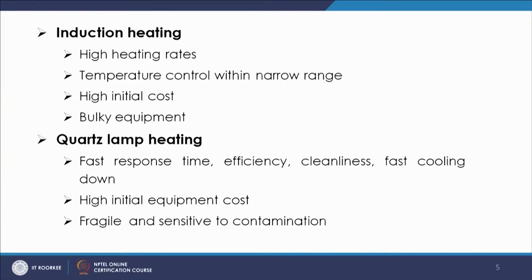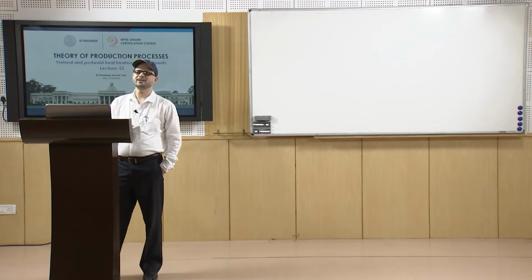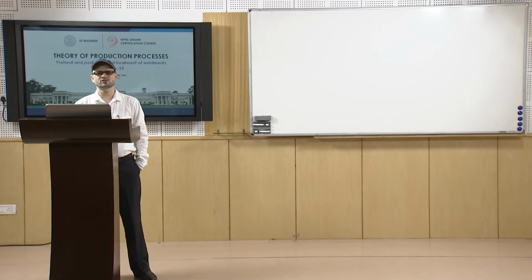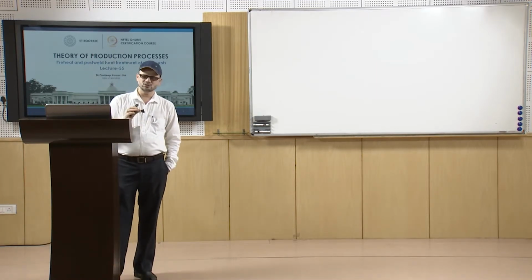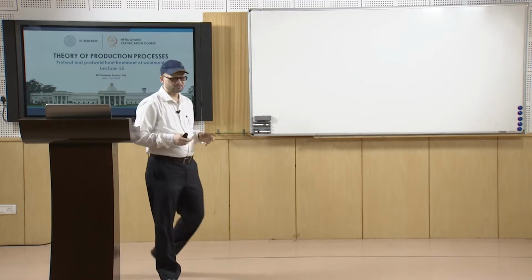Then you have induction heating. Induction heating is another mechanism by which you can do the heating. It has the advantage of high heating rates, and the temperature is controlled within a narrow range. But the disadvantage is that you have high initial cost, and the equipment is bulky.